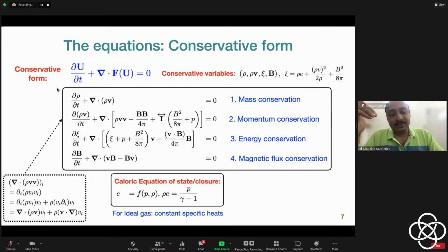However, if you have supersonic turbulence, meaning that you drive motions in your fluid that are higher than the speed of sound, then that perturbation will travel faster than the speed of sound and create shocks. So for supersonic turbulence, that becomes a challenge because you are starting to create shocks now. For those cases, the finite volume method becomes better, just for the stability of the numerical schemes.